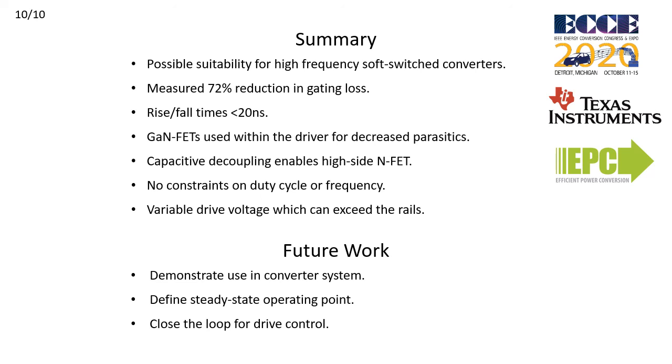Since conventional bootstrapping techniques are non-applicable in this design, here we described a capacitive decoupling technique which allows power delivery to the driver of the high-side N-channel device in the driver's output stage. Furthermore, relaxed clocking complexity and a variable frequency and duty cycle give versatility and extend use case applications. Moreover, this driver exhibits gate voltage amplification with both positive and negative peak voltage values being independently tunable through drive voltage adjustments.